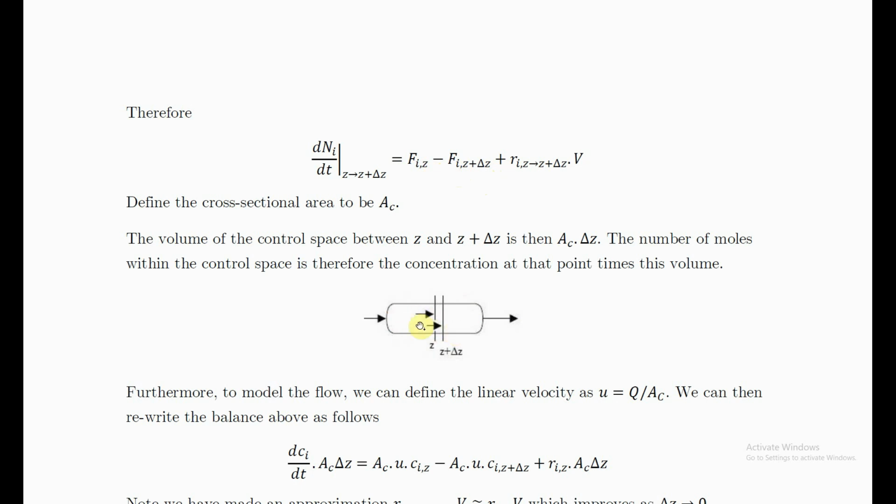The way I'm pointing here, you might have thought, isn't this just 5 cubic meters here and another 5 cubic meters going out there. But we are talking here about the molar flow of specifically component I. So yes, the fluid is being carried through, but arriving here might be 2 moles per cubic meter of component I. And then maybe I is reacting here and coming out here is 1.8 moles per cubic meter of component I. So these are generally different.